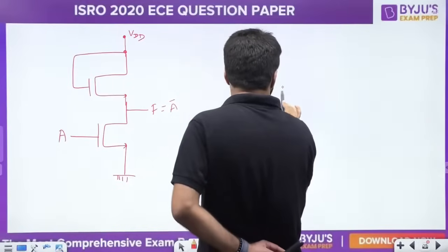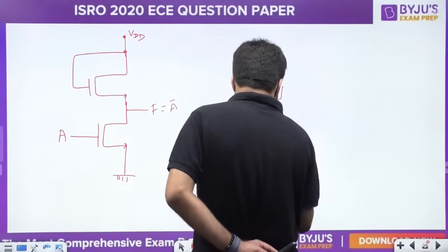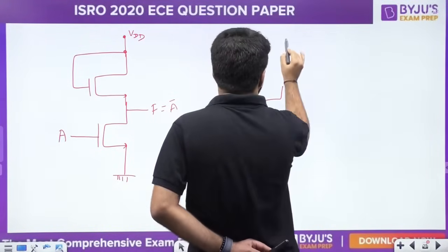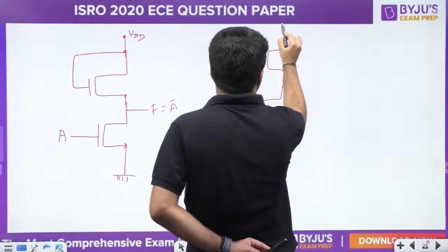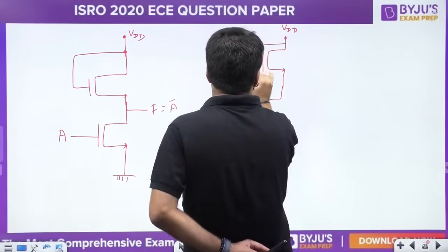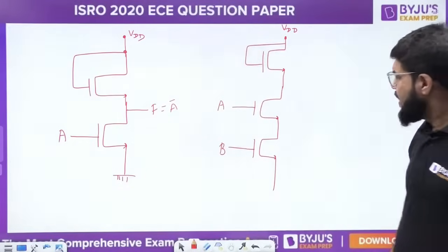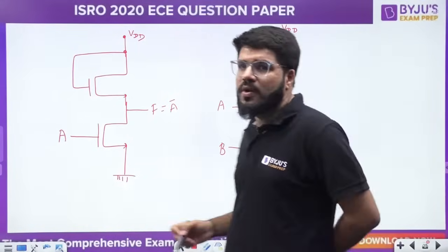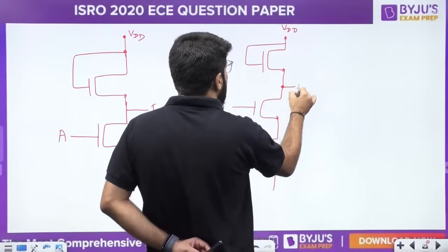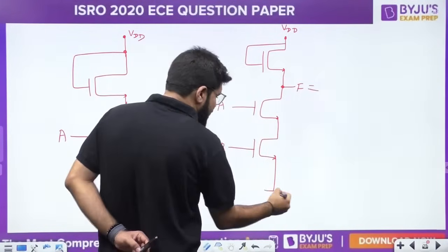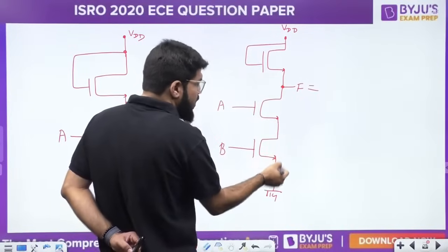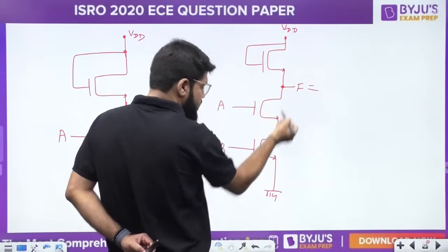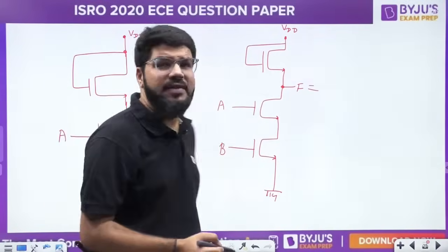Similarly, guys, a quick recollection. This is your NAND gate. It is not AND, it will be NAND actually, I'm sorry. Whenever both the inputs are 1, 1, then the circuit is complete, meaning both the switches are closed and the output is connected to the ground. There will definitely be current flow and a voltage drop. This will become 0 because it is connected to ground. So when both the inputs are 1, 1, only then is the output 0.